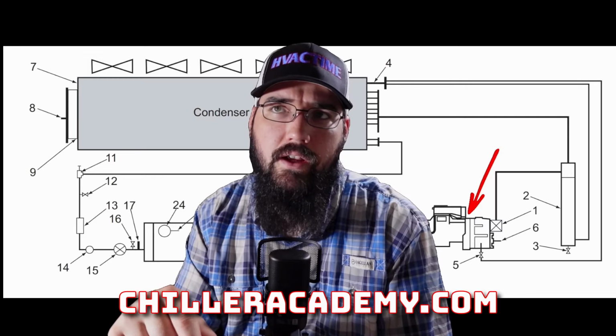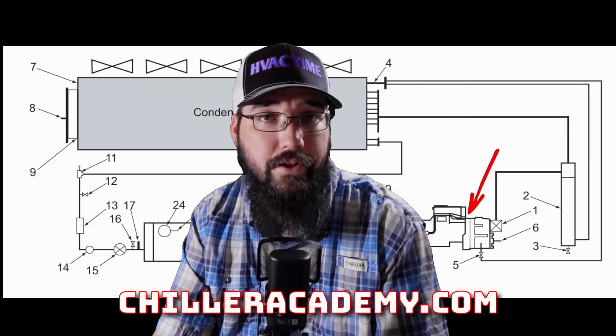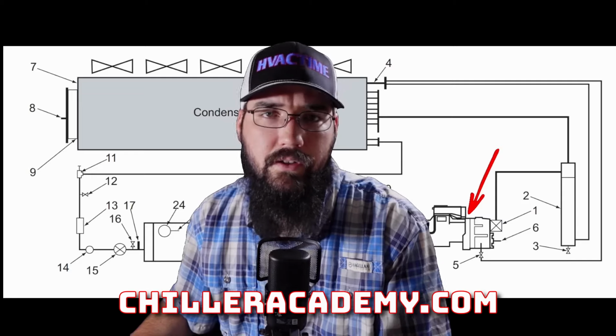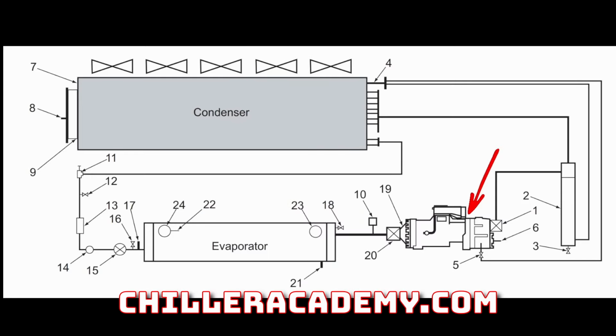And when we get into compressor design, we'll talk about some of the other cooling options like liquid injection. We start to see that introduced at a screw level, which is not something we would typically see on a chiller system with, say, a scroll or a reciprocating. So to recap, when the chiller needs to bring the compressor on and we have our leaving water, we're going to move our slide valve, if it is slide driven, all the way to an unload, and then we will slowly load the compressor until we achieve our leaving water set point.